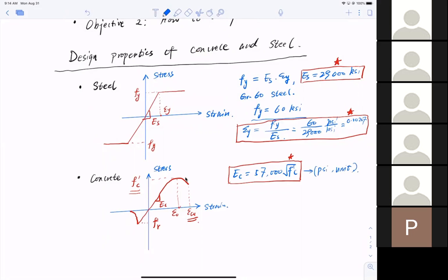Most of our equations, let me repeat, most of our equations use psi. So just a hint. That's the Young's modulus. Now I want you to know that comparing the Young's modulus of steel versus normal concrete is called the modulus ratio. It is approximately equal to 8 times. So you've got to figure out steel is 8 times stiffer than concrete.